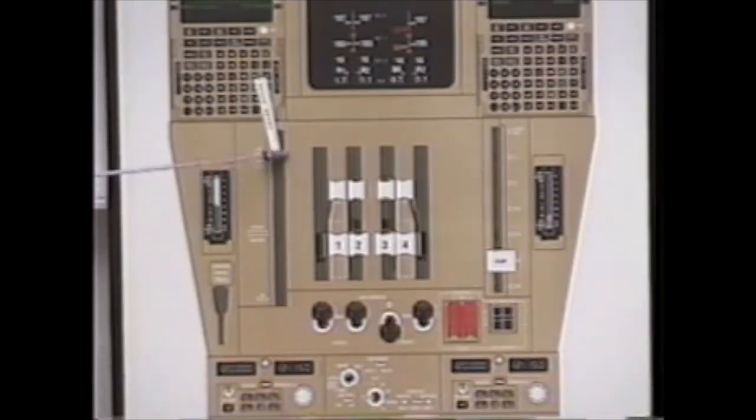Speed brakes. Speed brake lever in flight cannot go beyond the flight detent. It's physically impossible to bring it beyond that point. There is a lever lock there that prevents that operation from occurring. On the ground, the lever lock is removed so the speed brake handle can be pulled all the way to the up position.